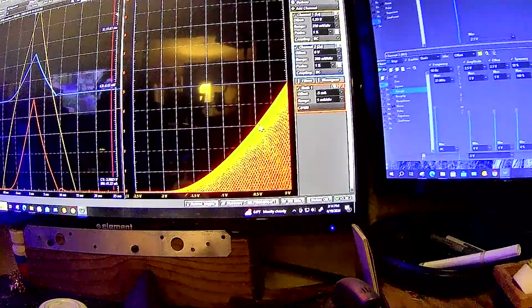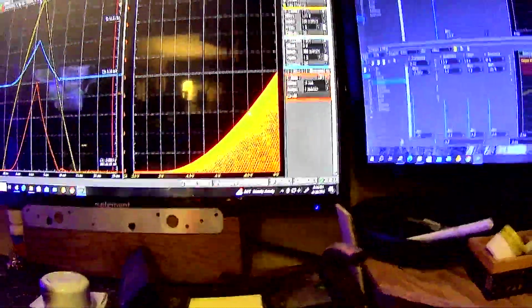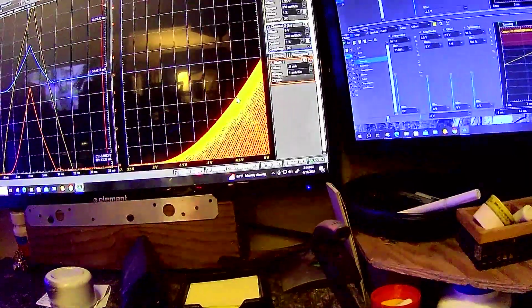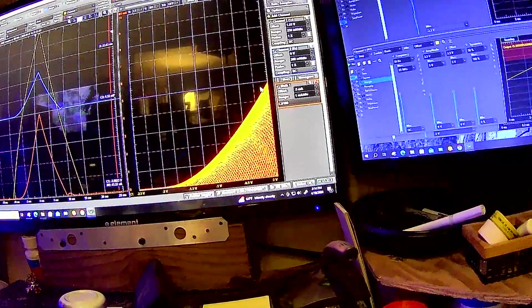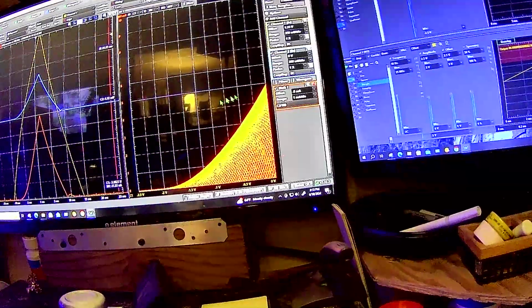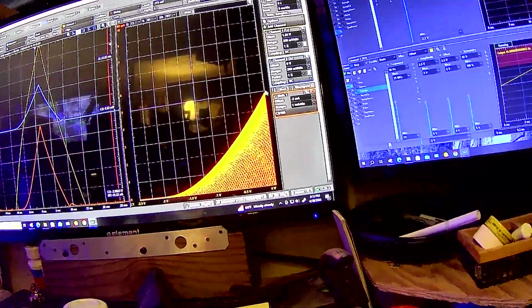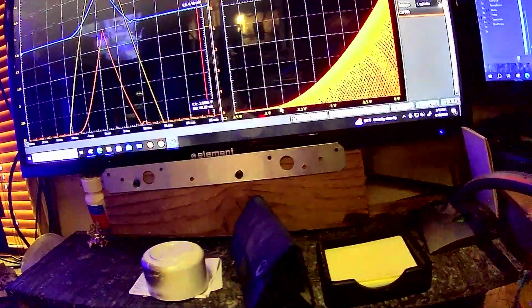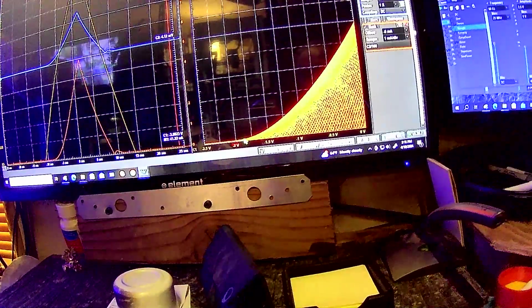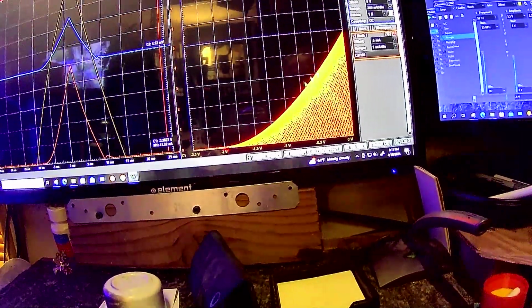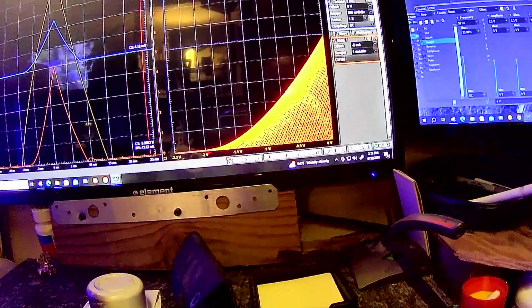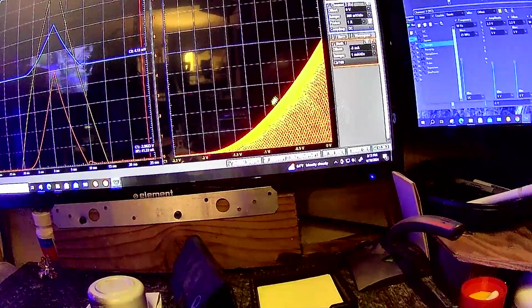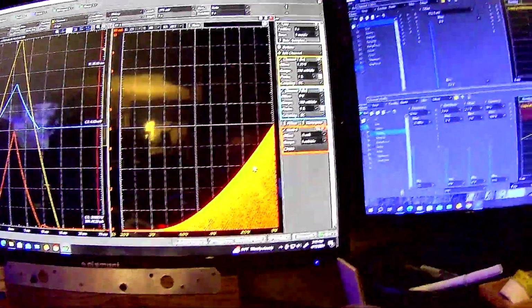But one of the things you would have difficulty estimating, by the way, is what the actual transconductance is, because the transconductance technically is the derivative of this curve, which you mostly see in textbooks. But if you've got these two parameters, what IDSS is, its maximum current, about 5 milliamps, and its pinch-off voltage, which is just under 2 volts, you can put those into the curve and maybe estimate the transconductance. But it's actually the derivative; if you had a curve tracer that could make a tangent line on this curve, you could estimate what the transconductance actually is.